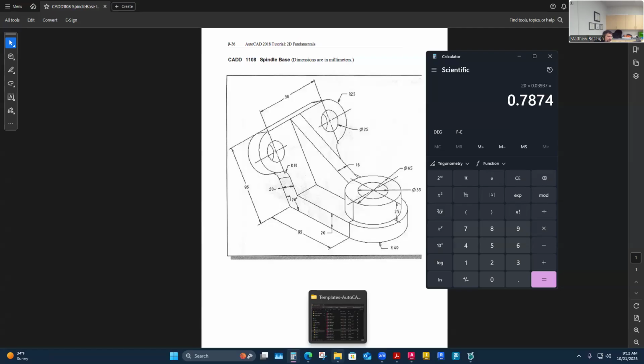And then the person like you or I or the engineer, we have to actually give them the right material, because it's going to stretch and pull. So sometimes we have to add extra material to actually hit the dimensions we need. Sometimes we subtract and sometimes we add material when parts are getting bent. You're reading about that a little bit in chapter 4 of theory, the manufacturing concepts of bending and forming metal and plastics. They stretch differently than metal.